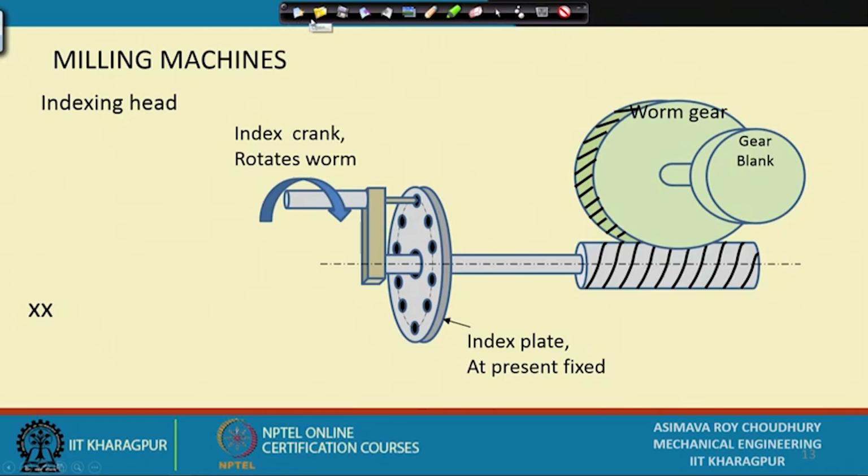Sorry, blank and crank. Crank means this handle which is moving round and round here. So, if I have to move by 1/4 of a rotation, I must be moving 40 by 4th of a rotation. Remember, 1 rotation, 40 rotations; 1/4 rotation, 40 by 4 rotations, unitary method. So, 10 rotations. This is the simplest one. Okay.